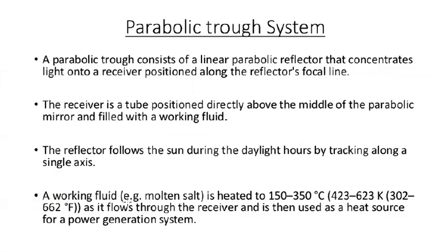which concentrate the sunlight by a factor of 80 or more onto a focal line, that is the middle line. Parallel collectors build up a 300 to 600 meter long collector row, and a multitude of parallel rows form the solar collector field. When we place a number of solar collectors in parallel, they form a solar collector field.